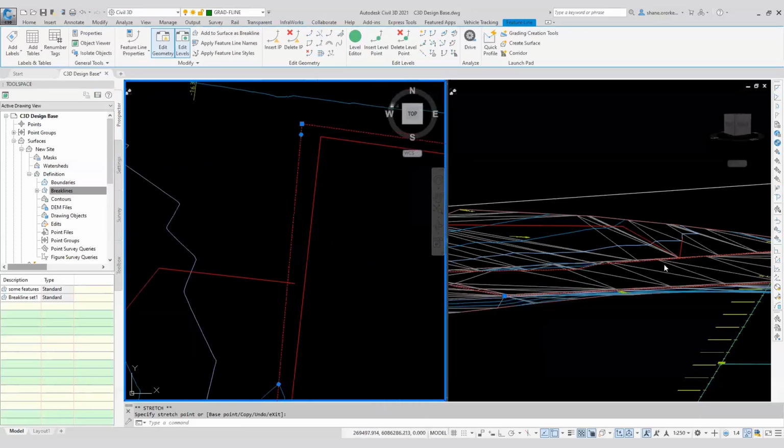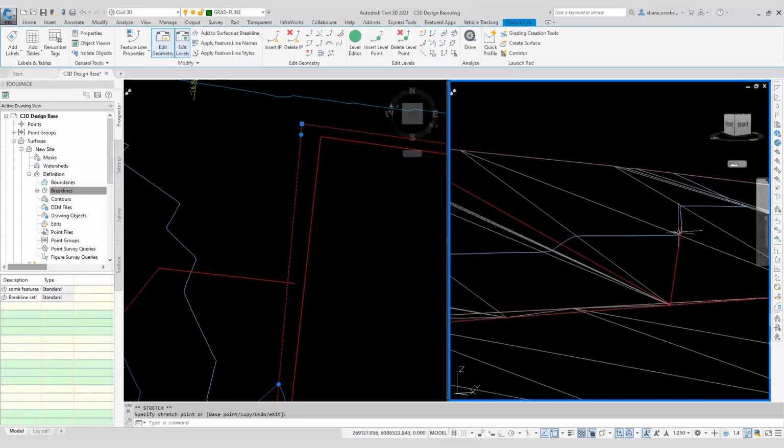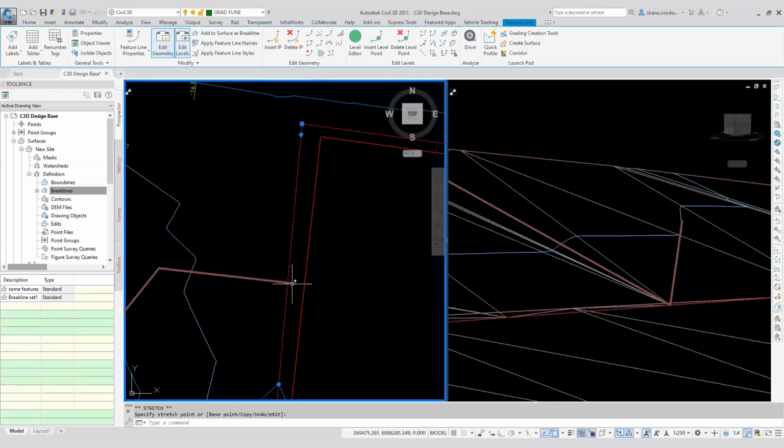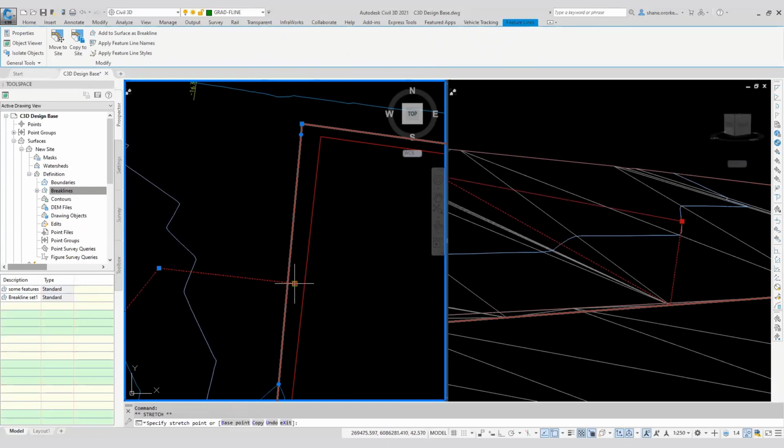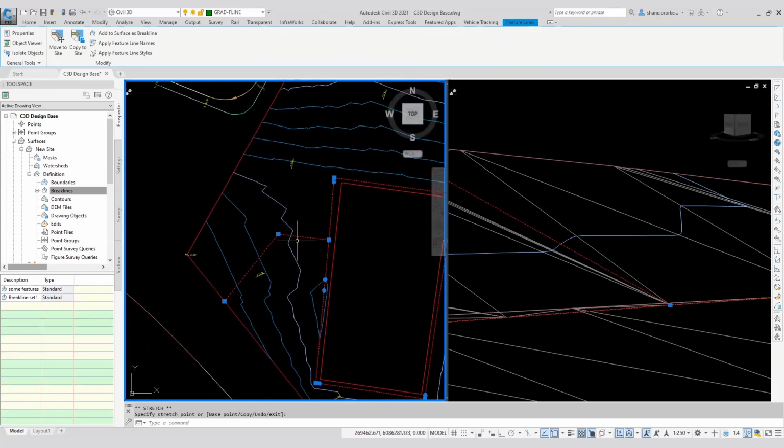You'll see that the footpath drags out. The bit that drags out is a big lift. So there's a big lift in this last little segment here. But the part where it touches this newly moved footpath edge, it's matching the elevation because it has to. So if I just pull that back and touch the edge, you'll see that it then goes and matches. But the last one you edit wins. So the last feature line you edit wins if they're the same style.